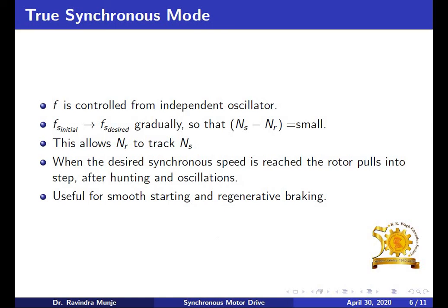So what is true synchronous mode? In true synchronous mode, stator supply frequency Fs is controlled from an independent oscillator. This is the synchronous frequency at initial value, and this is the synchronous frequency at desired value. So frequency is changed from initial value to desired value gradually so that the difference between the synchronous speed and